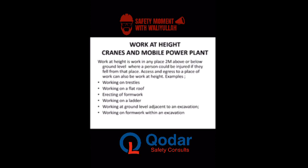We are coming to that aspect too. When working at height, work that involves 2 meters and above, we want to make sure that access and egress to that place is firmly planned and installed. If you're working with a scaffold, fine and good.